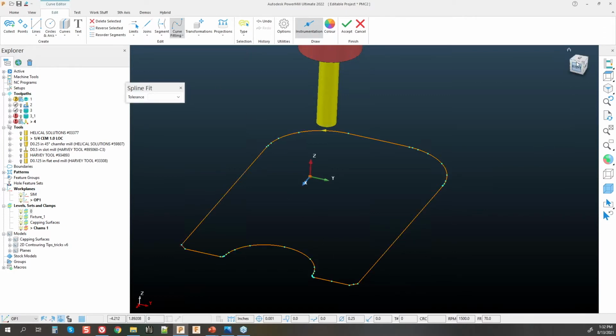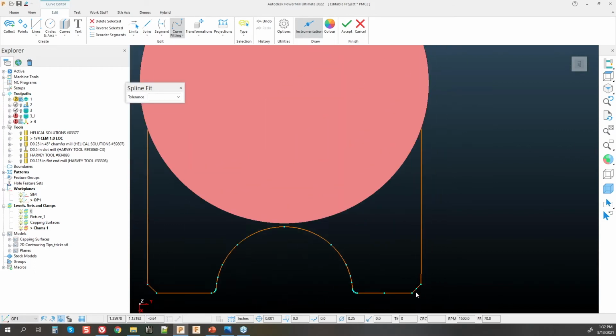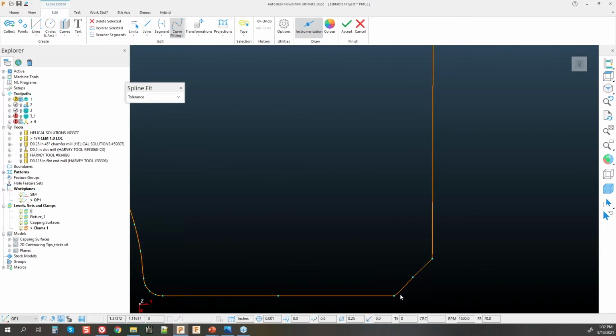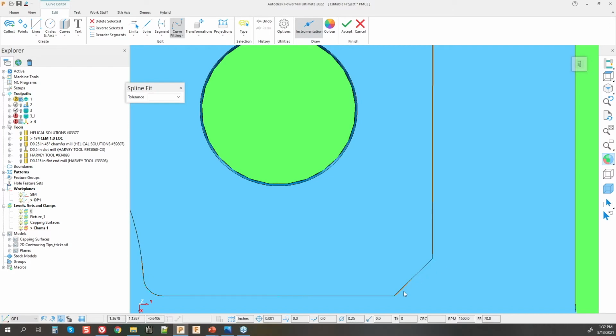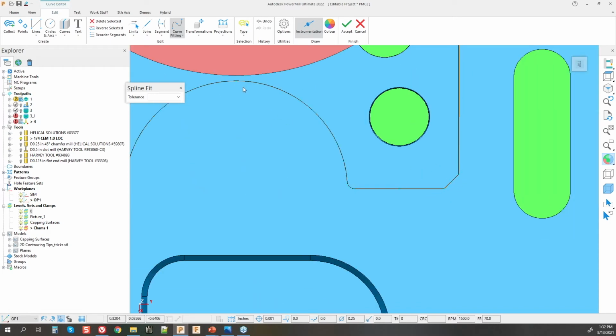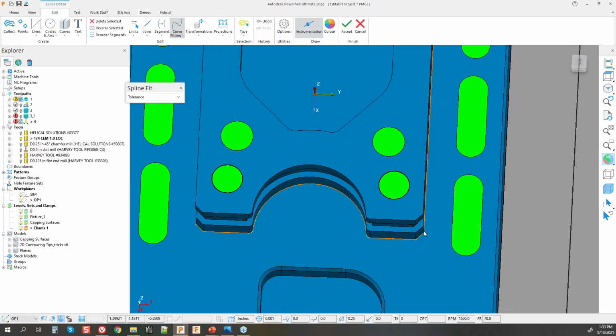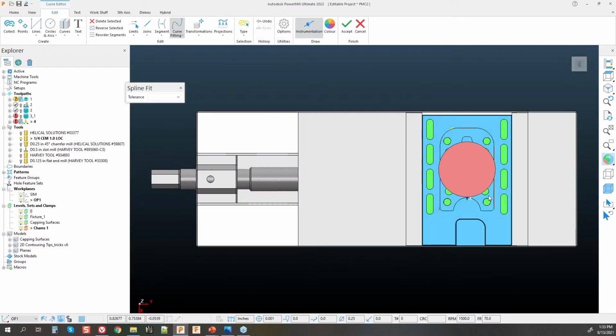All right. What this does is areas that aren't sectioned correctly within your pattern might end up actually turning into curves. And in this case, we do have one of those here, which within 1/1000 you can't really see. But if you're working on something that's tight tolerance or accurate, you'll see what it's done here is kind of turned that into a curve versus a straight line. All right, so it's important to note when you check your pattern, check your instrumentation, we're looking for these extra points. We're looking for those abnormalities within that fit of that curve.